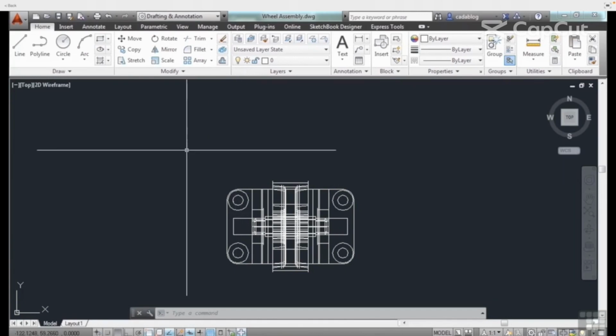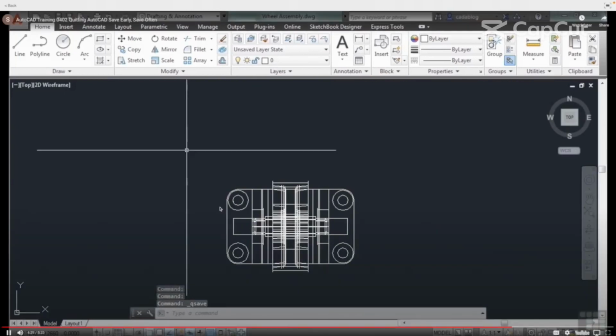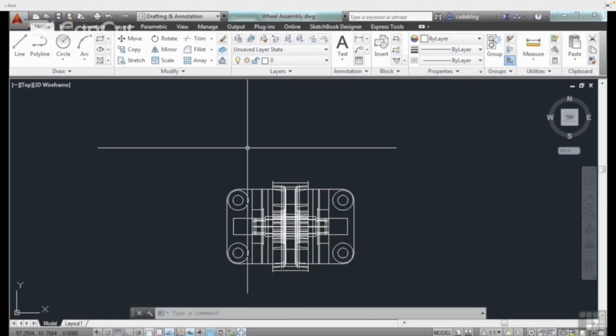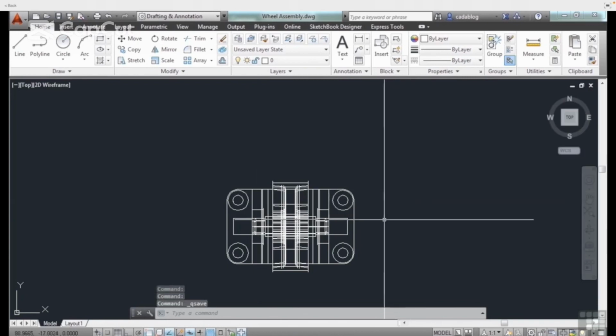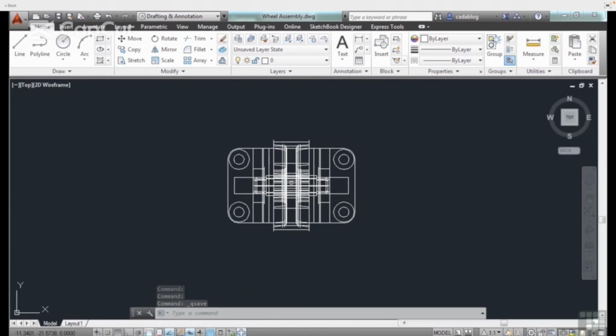Now, since we're working in Windows-based AutoCAD, you can also press Control and S at the same time. That's a Q Save. That's what I do. While I'm working, I'm drawing lines, circles, trims, edits, copies, paste, whatever. Control S. More lines, some dimensions, I'm moving, I'm zooming, I'm panning, Control S. I've gotten myself into the habit of using Control and S on the keyboard very regularly.